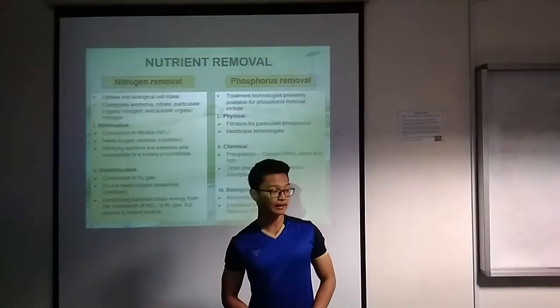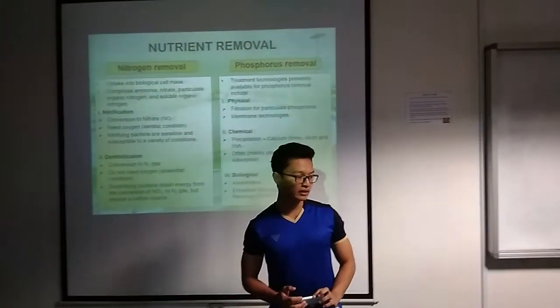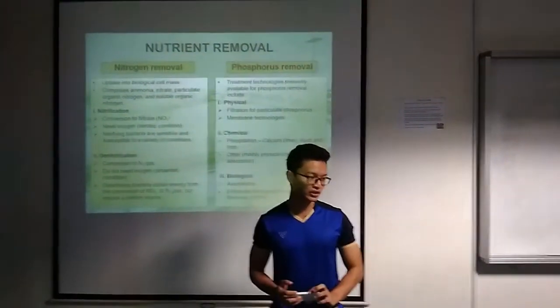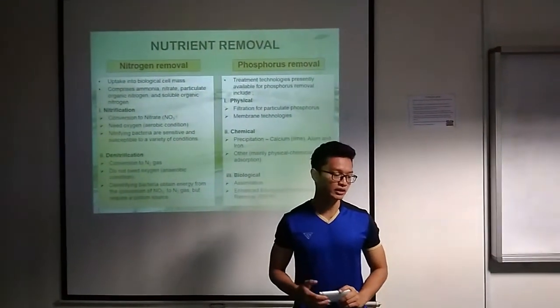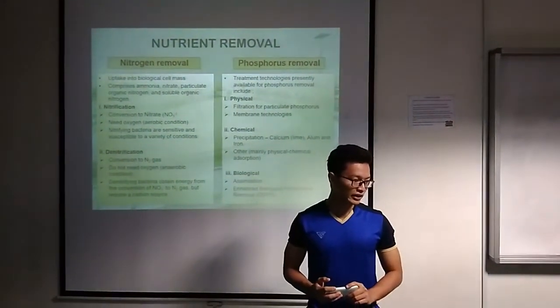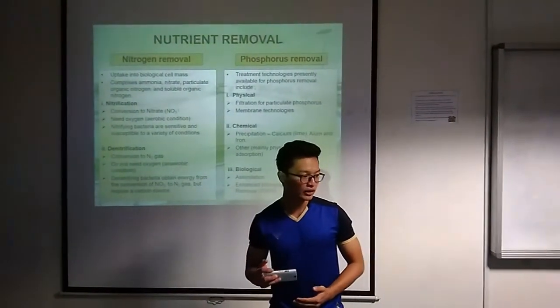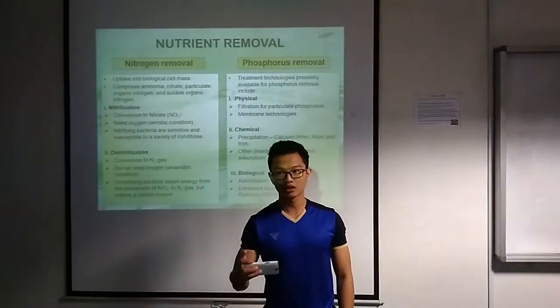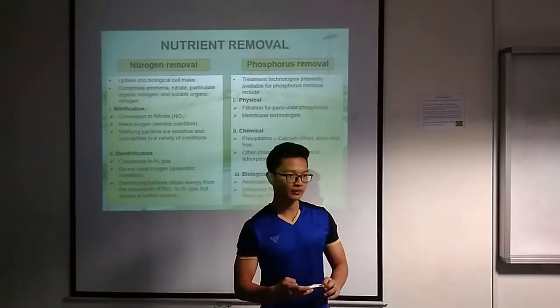Another step is denitrification. Denitrification is the conversion to nitrogen gas. In denitrification, it does not need oxygen, which is an anaerobic condition. Denitrifying bacteria usually obtain energy from the conversion of nitrate to nitrogen gas. However, it needs a carbon source as the essential element in the nutrient.